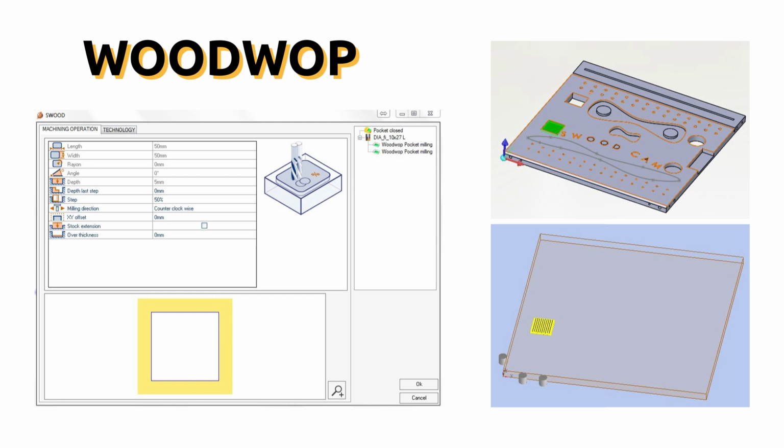Standard operations rely on the user to program the X, Y, and Z locations and give the trajectories of the toolpath, and this is how we predominantly program toolpaths if using a different type of post-processor such as G-code. As there is no transition from computer to machine, there is no need for cutter compensation, as this will be calculated at the machine level instead. The disadvantage of this is that you cannot simulate the toolpath to double check it before sending it off.